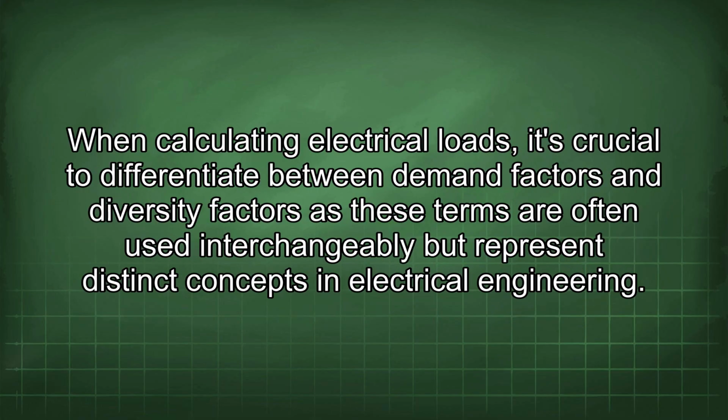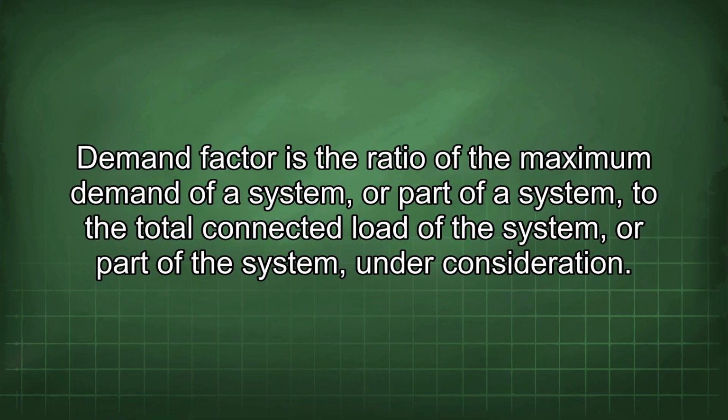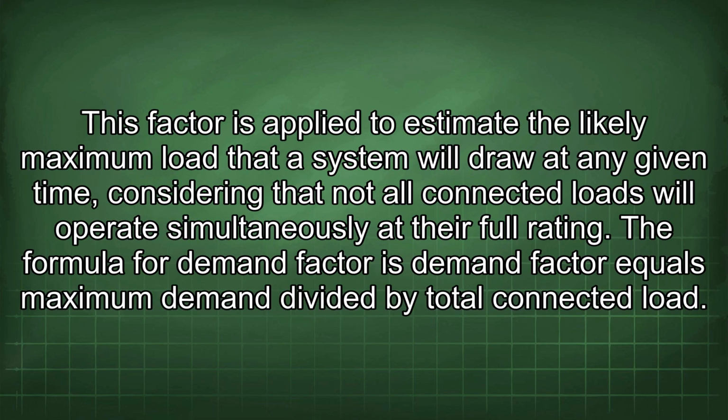When calculating electrical loads, it's crucial to differentiate between demand factors and diversity factors, as these terms are often used interchangeably but represent distinct concepts in electrical engineering. Demand factor is the ratio of the maximum demand of a system, or part of a system, to the total connected load of the system, or part of the system, under consideration. This factor is applied to estimate the likely maximum load that a system will draw at any given time, considering that not all connected loads will operate simultaneously at their full rating.